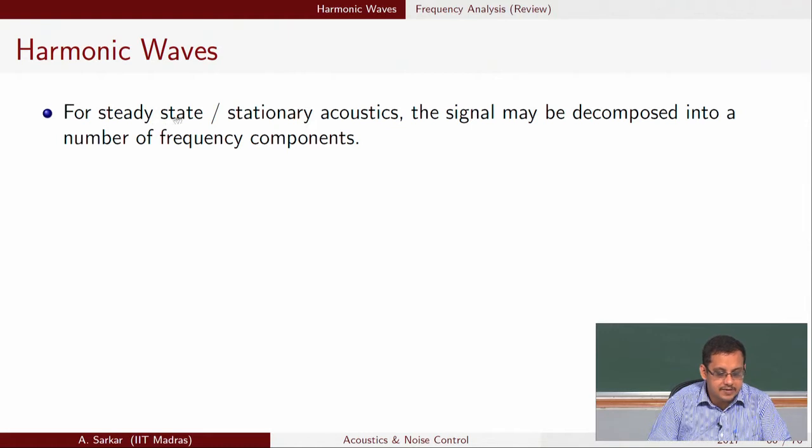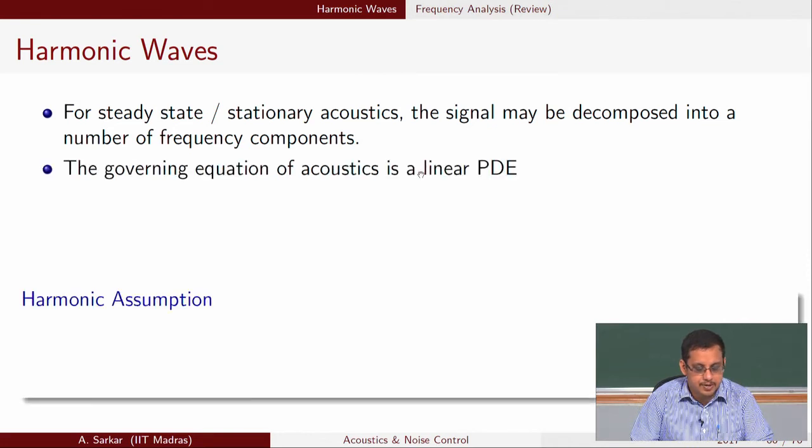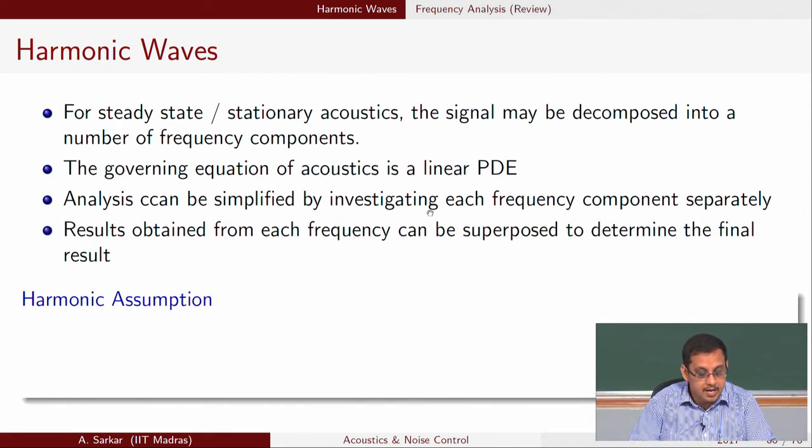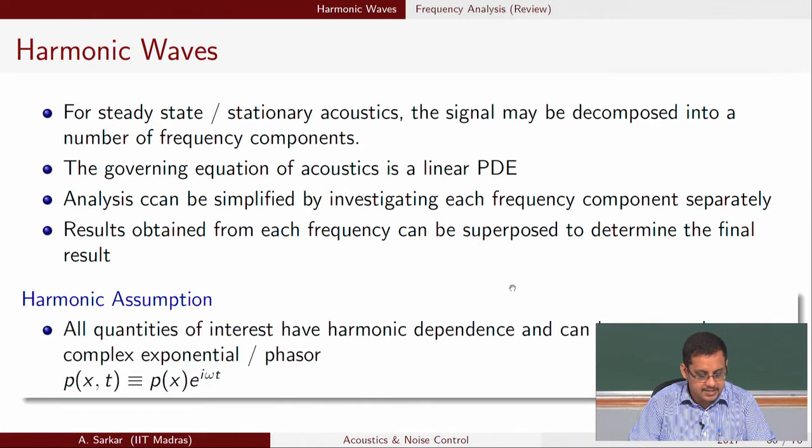So, by now we are convinced that for steady state or stationary acoustics, the signal can be decomposed into a number of frequency components, and we also know that the governing equations of acoustics is a linear partial differential equation. So, therefore, we bring about the harmonic assumption, which will come in a moment. So, the analysis can be simplified by investigating each frequency component separately. Rather than trying to analyze all the frequency components simultaneously, we will take the divide and rule approach, wherein we will analyze each frequency component separately, and then we will recover the total solution simply as a superposition. So, that is the harmonic assumption for you.